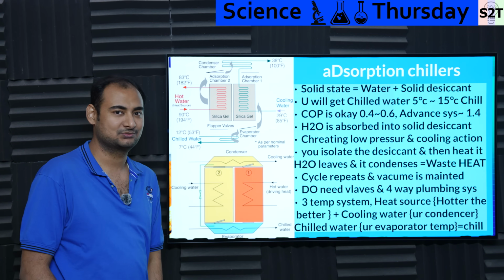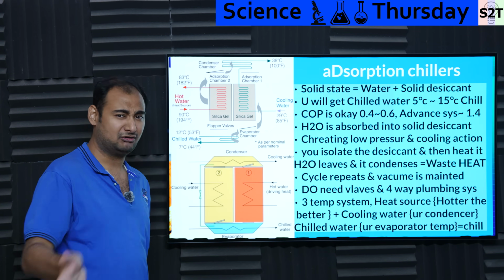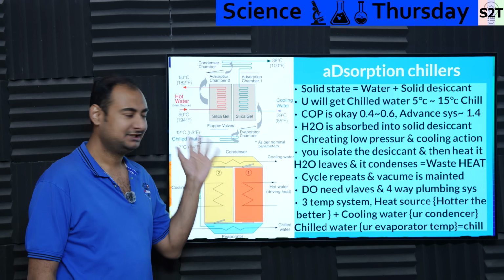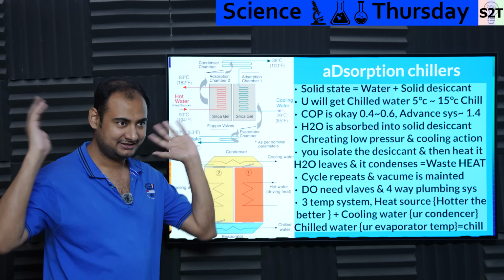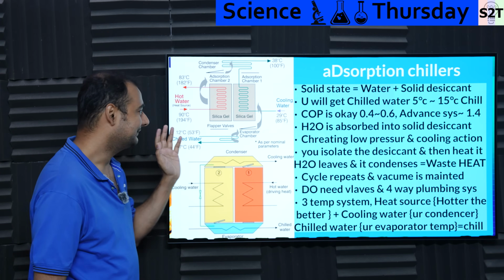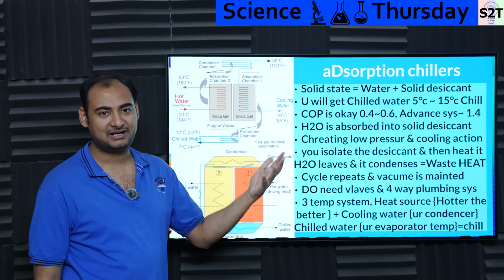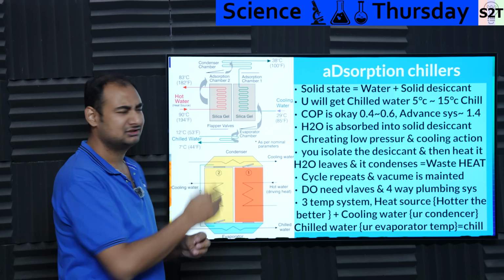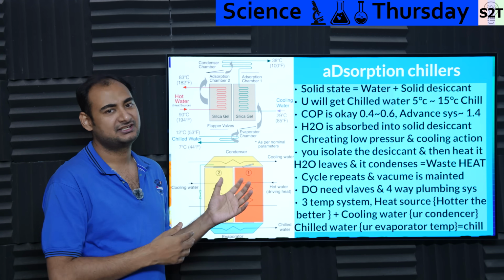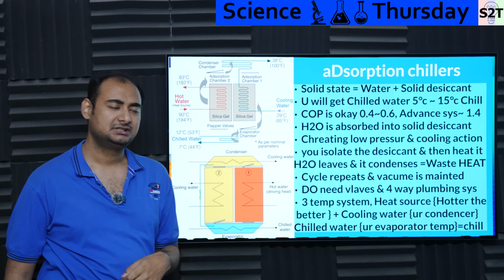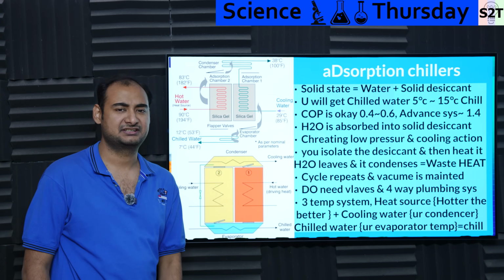I don't need much more than that, again, for household or even office, because the alternative is running AC at that point in time. And if it's running on the solar concentrator, not only is your building not getting solar heat, you are using the heat to pump the heat. So coefficient of performance is bad, but again, solar heat is free. And what about the pumps and all that? Those are negligible. For a multi-kilowatt system, like a 10 kilowatt unit, that puppy only consumes like 600 watts of power.